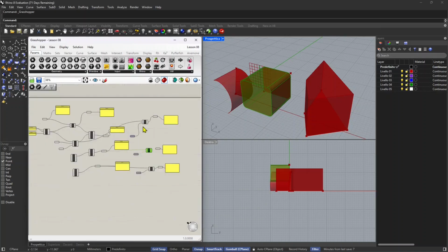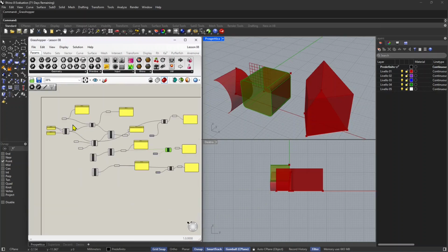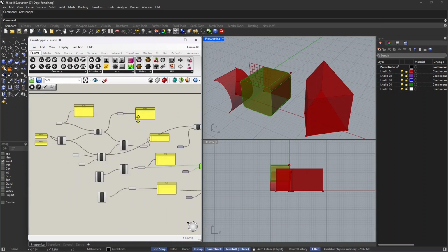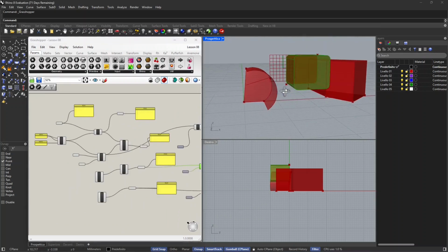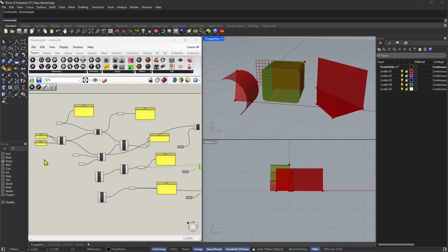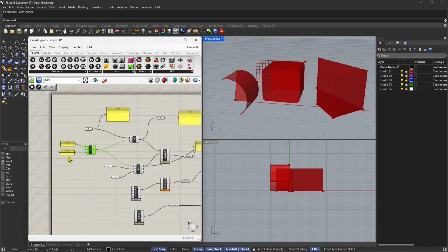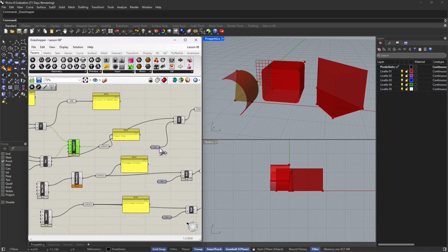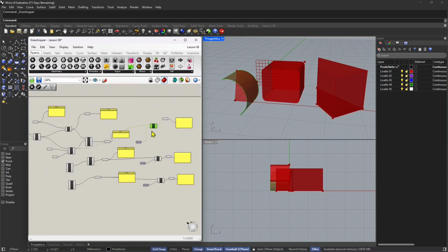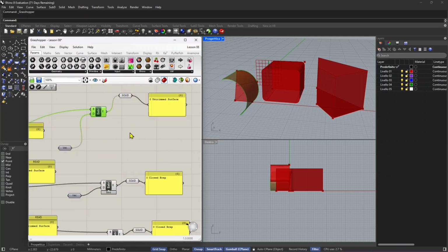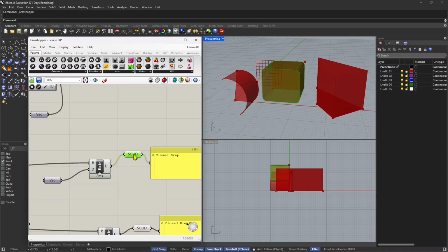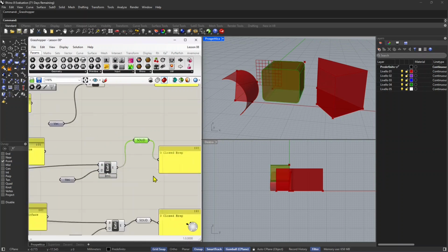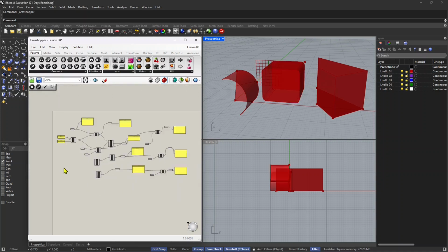In this video lesson about Grasshopper, we're going to continue to explore the basics. So in the previous lesson, we checked the basic algorithm here, and we explained the passages from going to a point and then transform that into a line, and then using a curve, and then a shape, then a surface, and finally how to get to a closed polysurface, which is also called a solid.